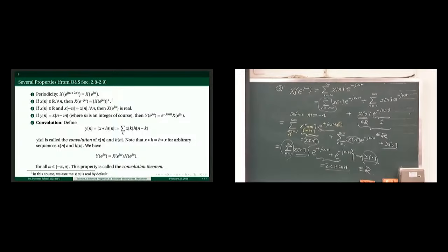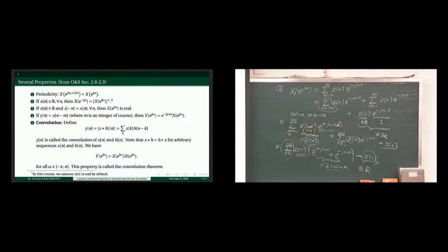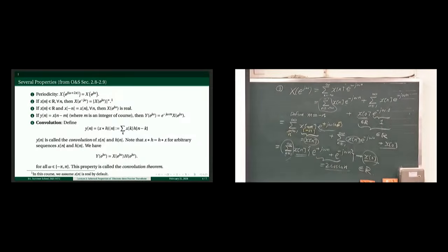Okay, so in this way, you can think of convolution as if we are flipping a signal in the time domain and then performing an inner product with the other signal, and then we flip and shift. After flipping, we gradually shift the signal by n samples and then calculate the inner product. The result is another signal.